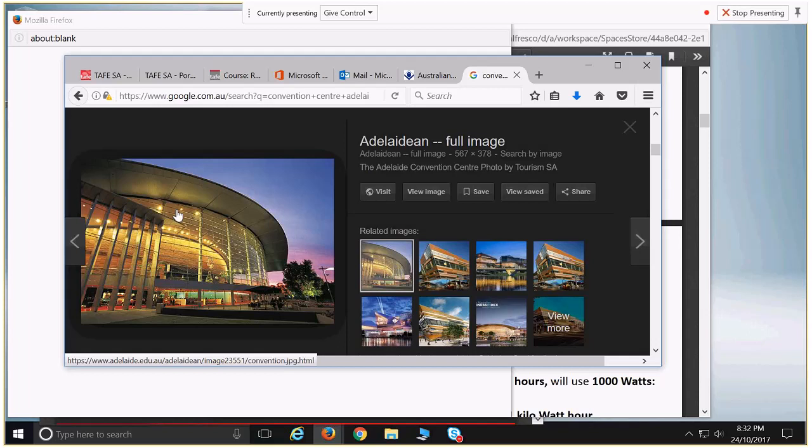So that enables these frames to be quite small, but span really long distances from point of support to point of support, like probably 6 meters or so, because they're hanging from these cables. Those cables are just going to be in tension, and that's going to support those frames in a vertical sense.